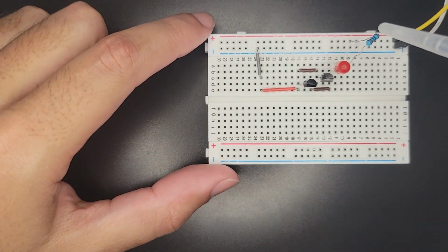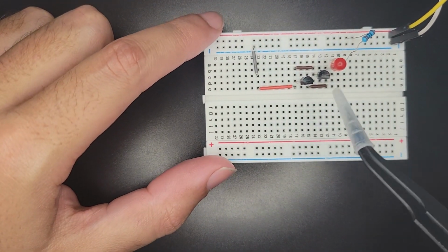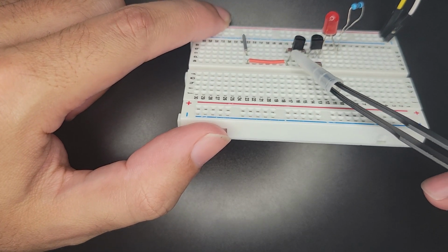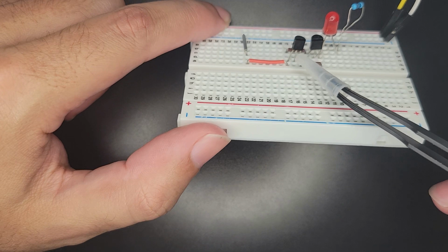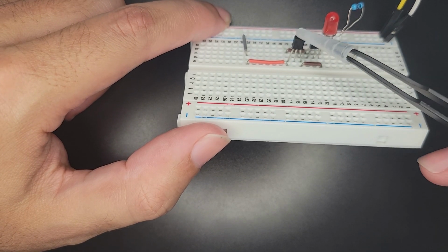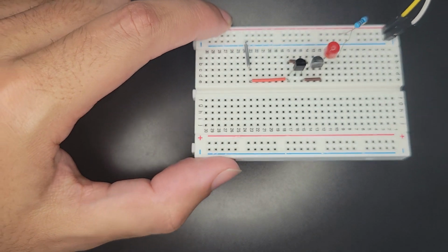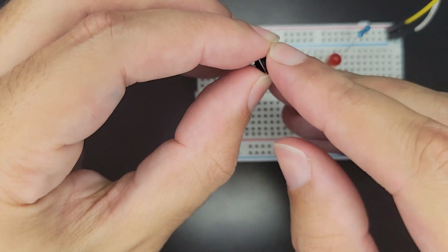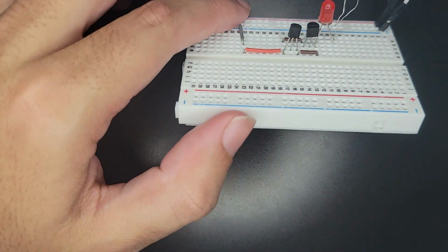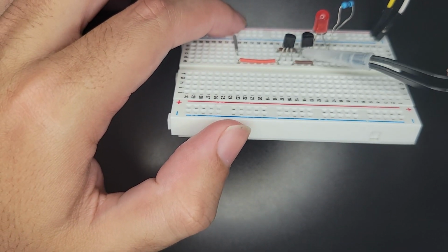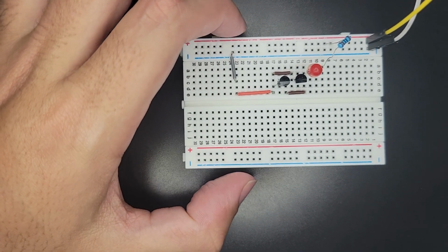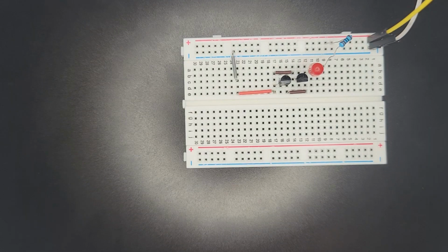Now, this should not work yet, right? Because, again, the transistors don't actually allow the collector to talk to the emitter until their base is energized. So these are switches, and the way that we press a switch, kind of like our old switch, right? We click and it turns on. Well, the way that we turn on the transistors is by powering up the bases, by giving them a high signal. So what we can do is get two more